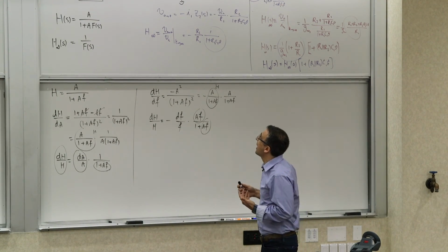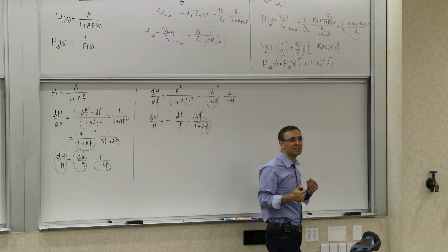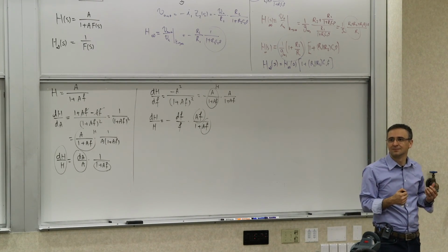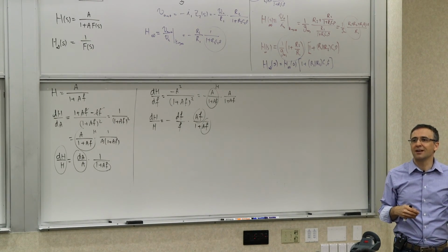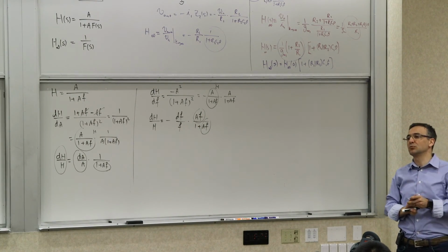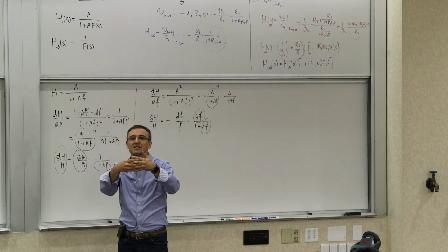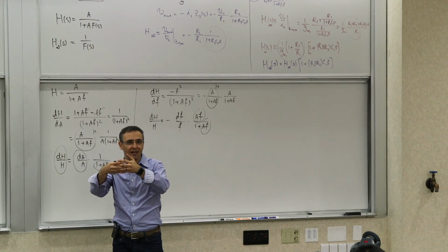That's why, when you design a feedback network, you want it to be defined in terms of parameters that you can control well. You want it to be defined as a ratio of two simple resistors that you place close to each other so they're at the same or similar temperatures. Or you interleave different pieces of them to be even more closely related to each other.